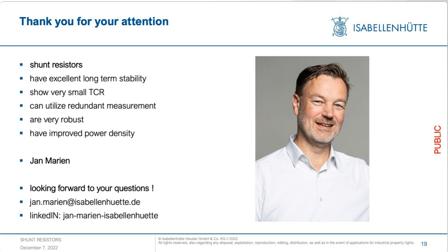And here it is. Why is temperature compensation at shunt level so important if it can be calculated in the microcontroller? Okay, this is also an interesting question. So if you do temperature measurement at the shunt level, so for example, if you use NTCs and calculate the temperature at the shunt level, and you know the TCR or the full TCR curve of the shunt, in fact, you can calculate the TCR by the microcontroller and compensate for the TCR.